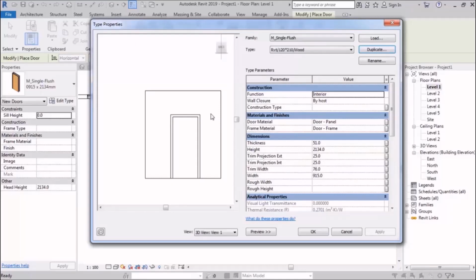Now, is everything perfect about this door? No, now I should enter the parameters. You see here, height 2.10. Pay attention to the unit. Now, it's millimeter. So now the width, 1.20, and for now we have nothing to do with the material.